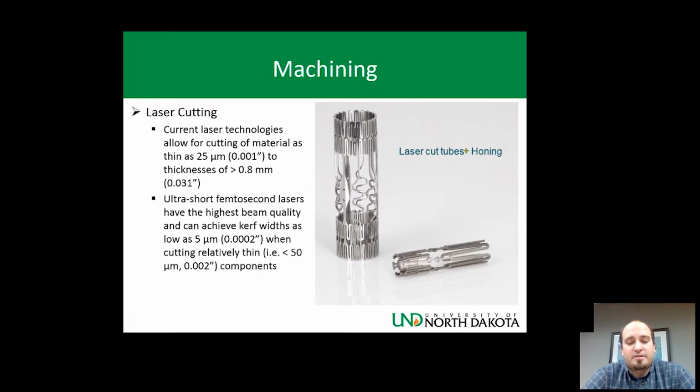Current laser technologies allow for cutting the material as thin as 25 microns to a thickness of greater than 0.8 millimeters. The ability of the laser system to cut fine complex geometry largely depends on the motion system and the spot size of the focused laser beam.